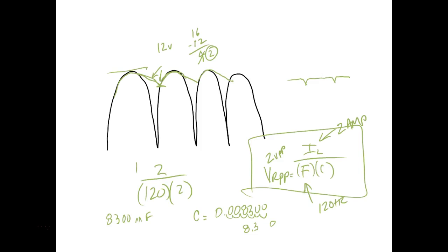So we're saying we could stand 4 peak to peak, but we want a safety margin built into it. If I calculate a capacitor that will give me 2 volts peak to peak, then it's not going to get down into the regulator, right? So we've got a safety margin of 50%. Does that make sense? Then we can choose our capacitor and round up to the next size, and we're going to be okay.